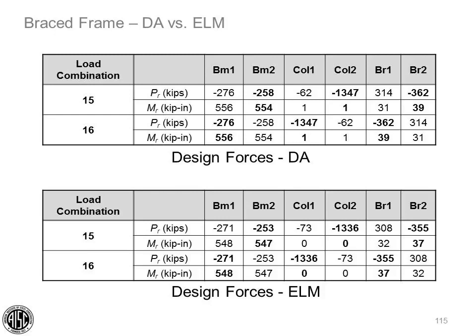Note that the direct analysis member forces are typically slightly higher than the effective length method forces. For the direct analysis method, K is always equal to 1. For the effective length method, since this is a brace frame, K is also equal to 1 for these members using the effective length method. So in this case, with the brace frame, the forces are only slightly higher for the direct analysis method, K equals 1 for both methods, and we end up with the same member designs for each.